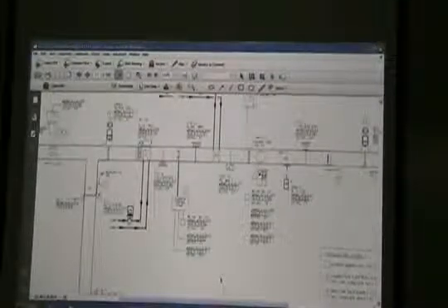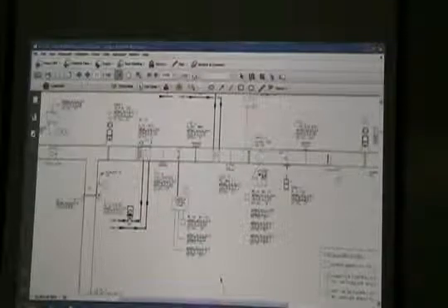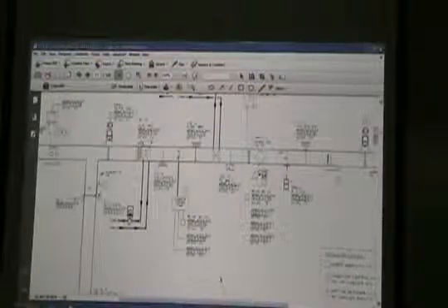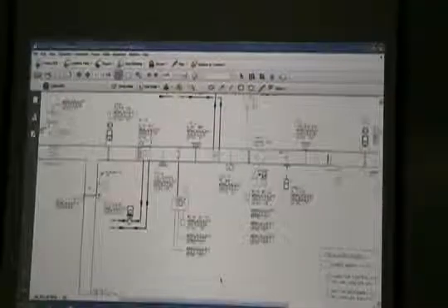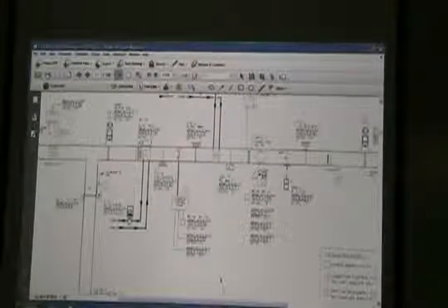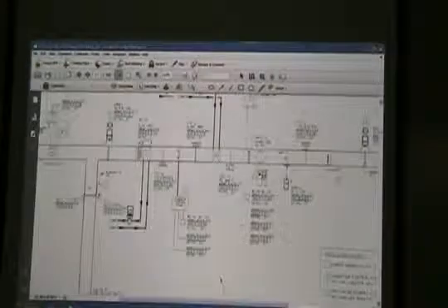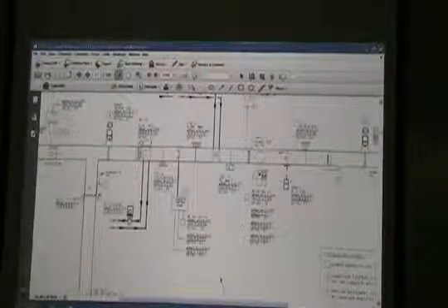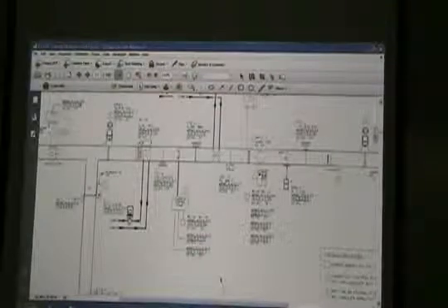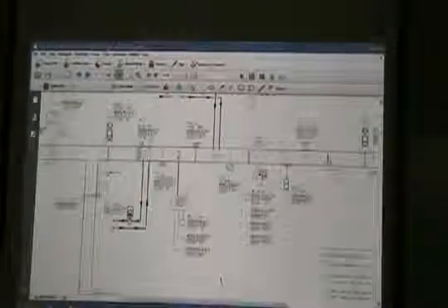And the reason this is such a small area compared to this is I have no pressure drop right here. So I've got some kind of pressure drop across that coil, so I can do much less area, probably 20% of the area here, because it's free air. It ends up probably equaling the pressure loss, because I've got all my air coming down here, then I've got to force it through that opening right there. Well, the manufacturer designs that opening to be probably about the same pressure loss as that coil.